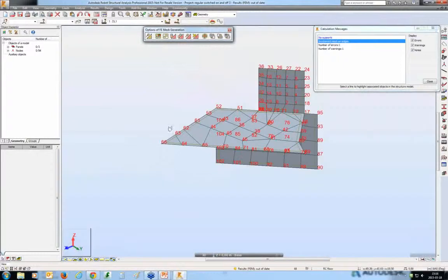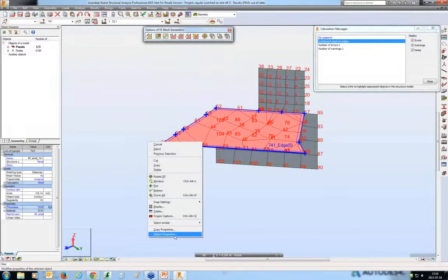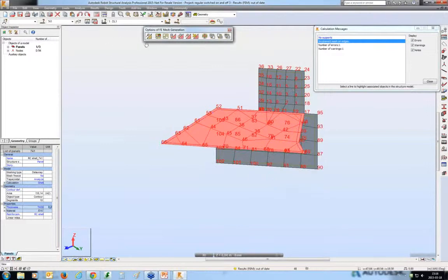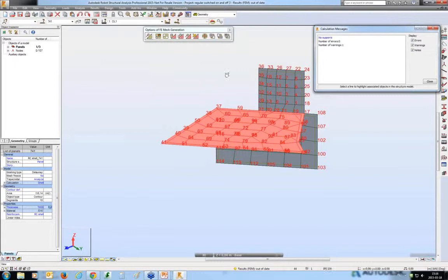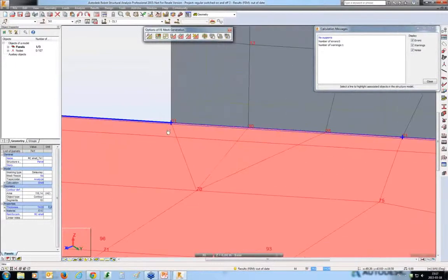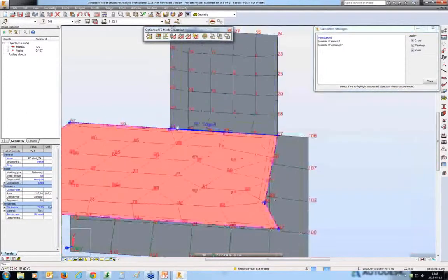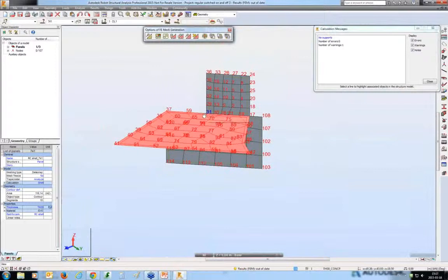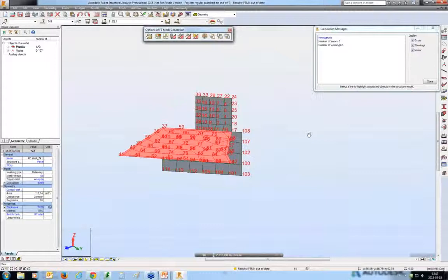So what I'm going to do, I'm going to check what parameters I assigned to the selected panels, and meshing parameters include regular mesh. I will switch off regular mesh, and I will just generate the model again. And this time, okay, the different algorithm handled the situation in a better way, and there is no excessive number of elements or nodes in this location.